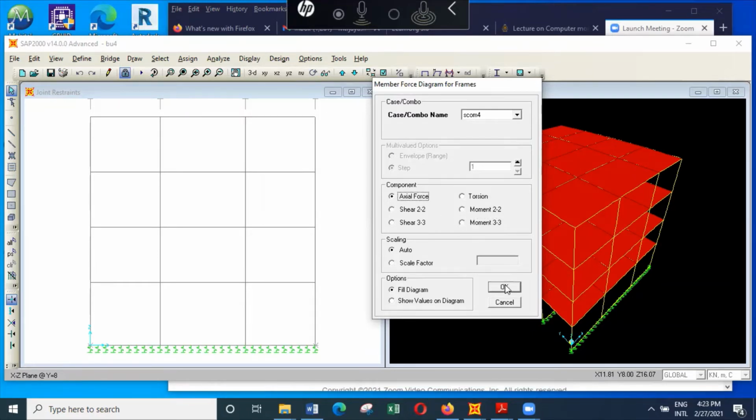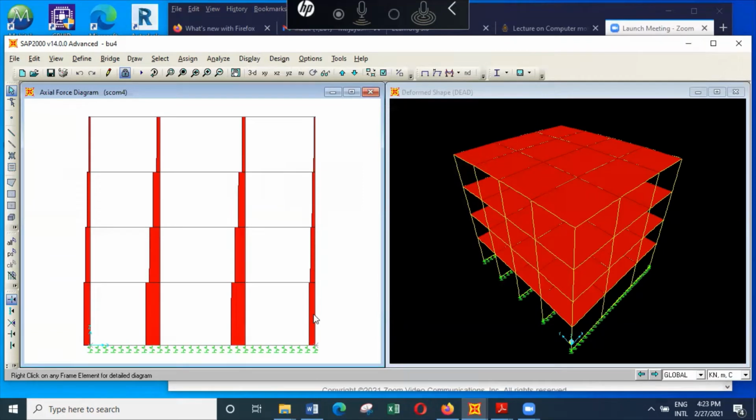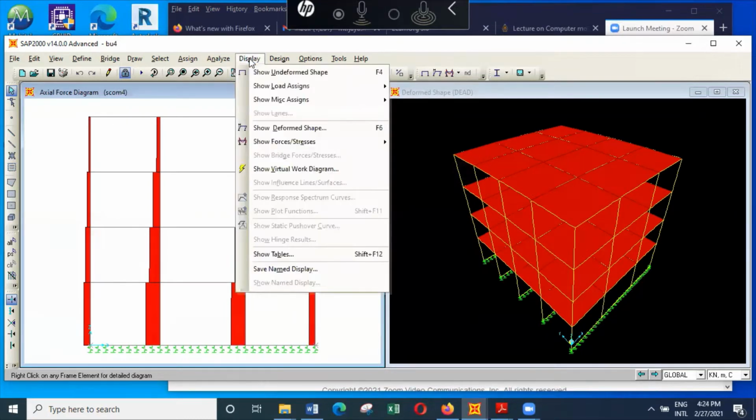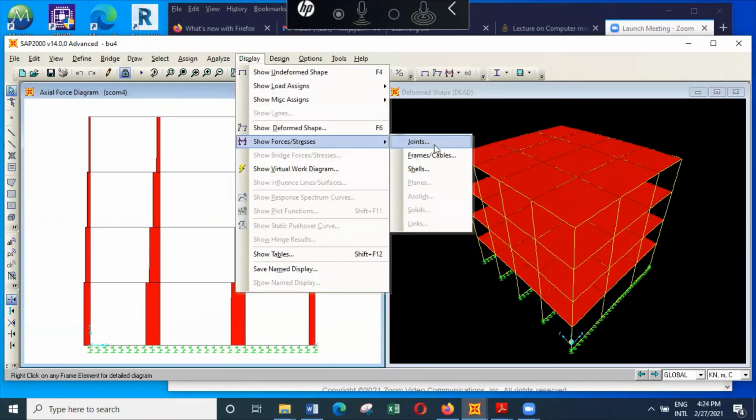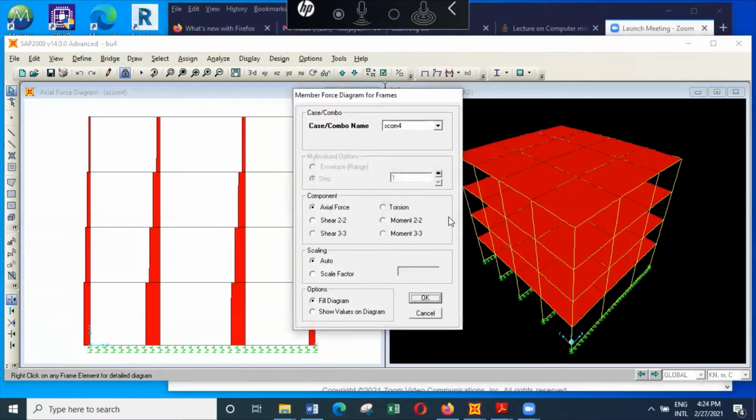And you can just have a look at the axial forces as well. Sometimes they would have changed slightly. And you can see the axial forces have changed slightly. Because of the deformation of the structure, the axial loads have changed slightly. And accordingly, there will be some minor change in the bending moments here as well. And then I can also look at the bending moments.